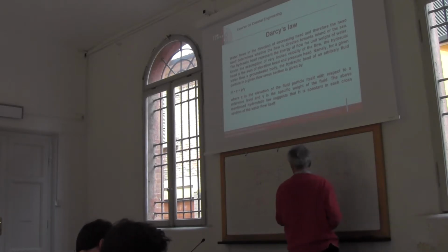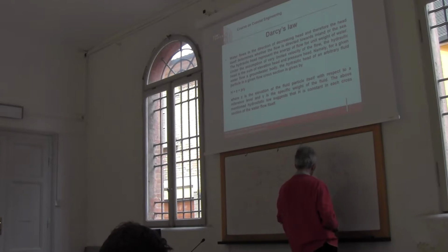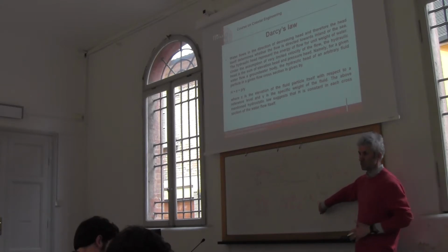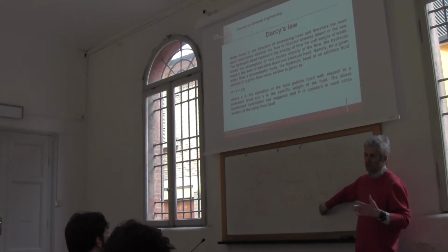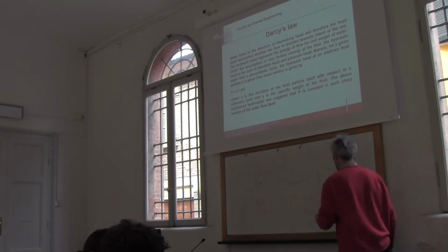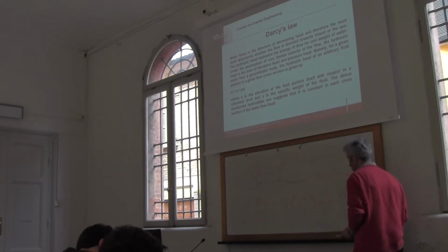So basically we may write that this is more or less equal to lowercase hf, which multiplies 1000 divided by 1025 minus 1000. This is a typical specific weight of salt water. It depends on the salinity, but a typical value is 1025 kilograms per cubic meter. And therefore, this is more or less equal to 40 hf. This is the relationship that I wanted to derive.